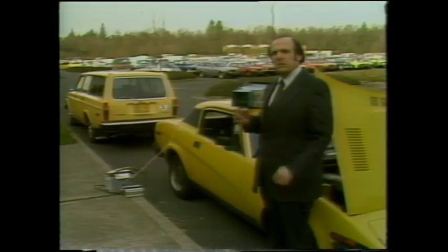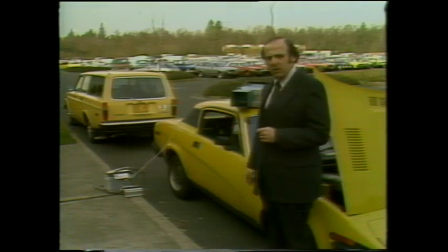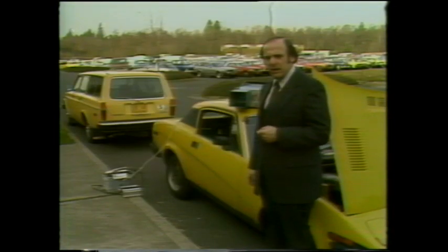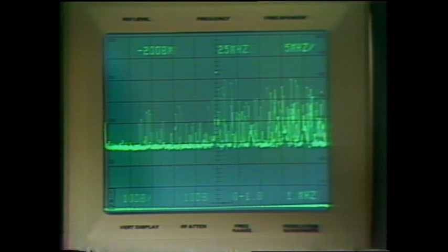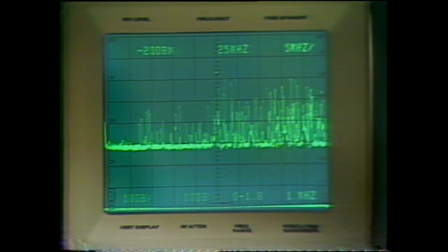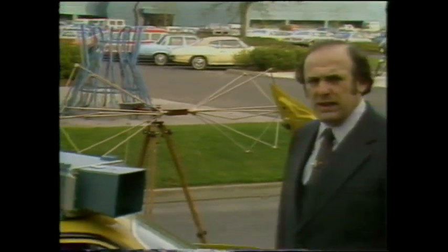In making this measurement, we're using a 492, and it's being powered by a car battery and an inverter. In this way, we're not dependent on any outside power source like that from an adjacent building. In making the measurement, the noise is peaking between 25 and 45 megahertz. We have a broadband peak, and the noise level is -40 dBm. To convert to dB with respect to a microvolt, we add 107 dB to the measurement and get 67 dB above a microvolt. Now the level has to be normalized to a 1 megahertz bandwidth. Finally, in this measurement, you have to take into consideration the antenna correction factor.